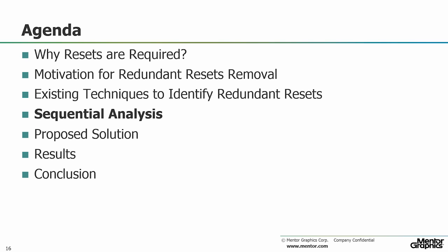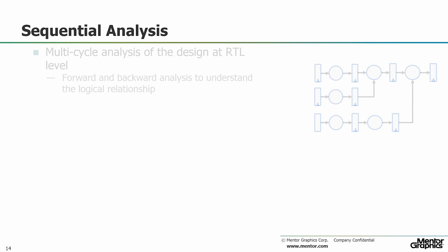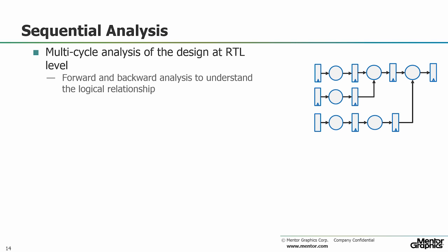Sequential analysis is a process of multi-cycle analysis of design at RTL level. Using the sequential analysis, forward and backward analysis of the design can be done to understand the logic relationship between the registers. One of the applications of sequential analysis is clock gating of registers.